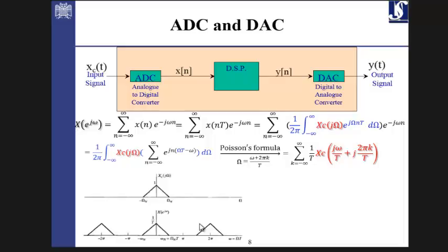But let's see, if you want to study such a process, we need to have a clear mind of what's actually going on with the signal. How can we investigate those tasks which are performed on the signal in a mathematical form, in order to follow that in analytical form? So the input signal, which is continuous, after passing through the A to D converter, is actually changing to a discrete form signal x of n.